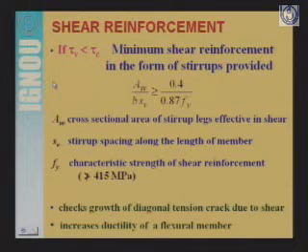Asv is the area of stirrups. Stirrups are the shear reinforcement or steel that is provided in the form of a loop, and generally this loop is taken around and along the section. So generally two-legged stirrups are provided that we call vertical stirrups.